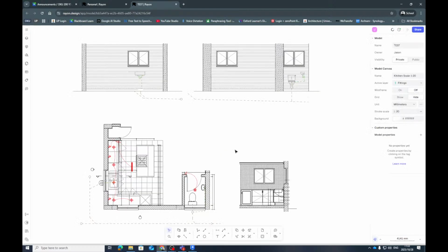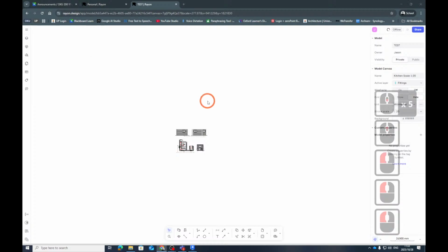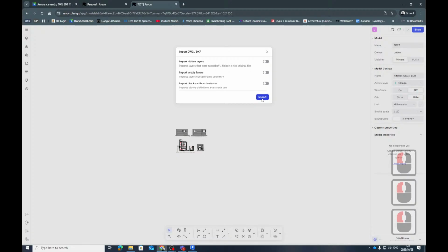You just want more construction type sections, because those are really design sections, as in those examples I've given you. Exactly that. So this is all from AutoCAD, but now it's so easy. File, import, DWG, and then you just throw it in there from desktop. The only trick is the scale, but watch. When you bring it in, you can scale it once it's in already.